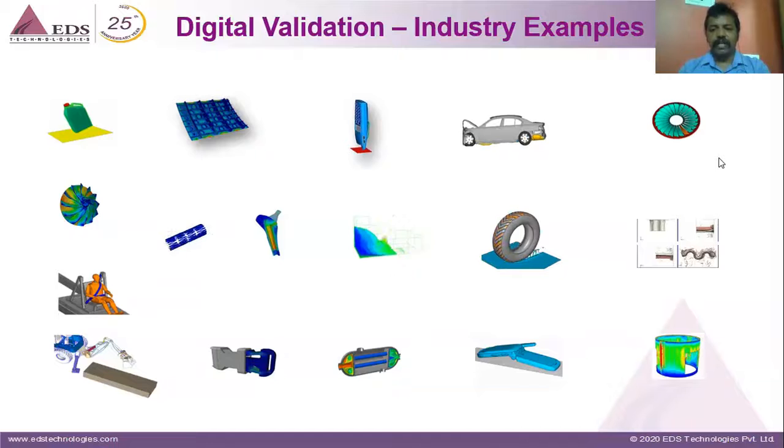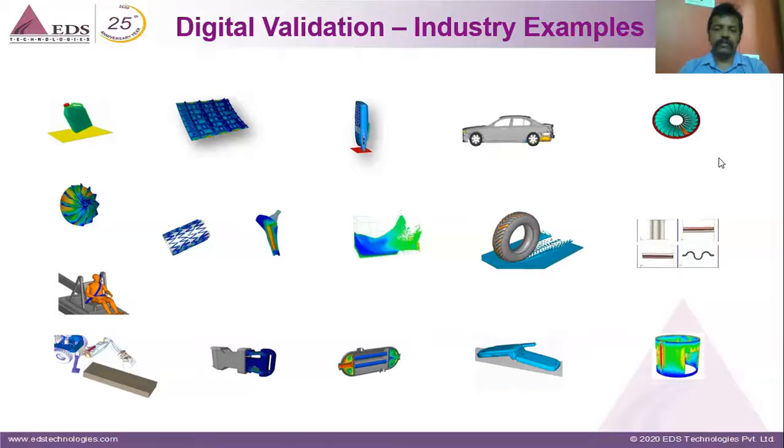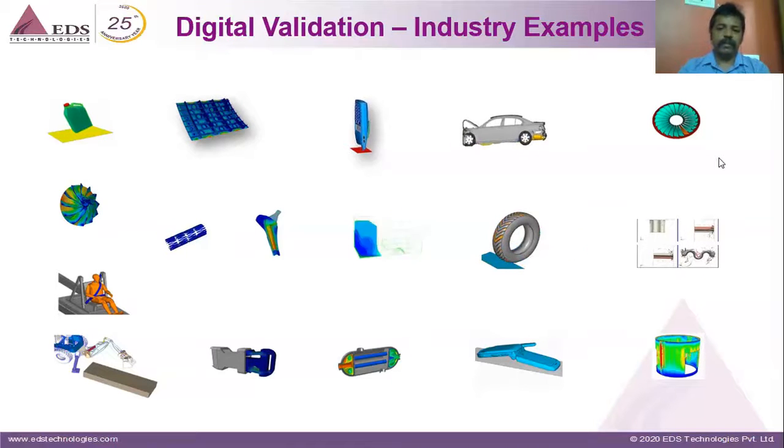Next, you have a tire which rolls on fluid, which is nothing but hydroplaning. So how do we simulate it? Again, we have co-simulation options here. We have a tire as a complete rubber material. We can give the hyperelastic properties, and then we have this fluid which is nothing but CEL. And I have the threads on the tire where I can understand how these threads help the fluid spill away so that the rubber patch exactly comes in contact with the tarmac.